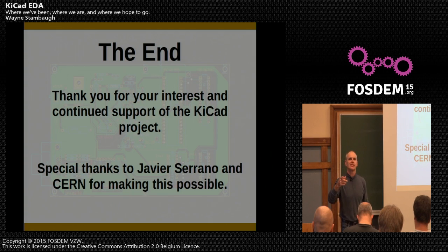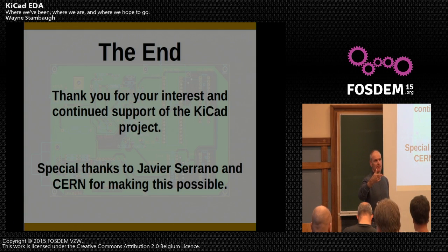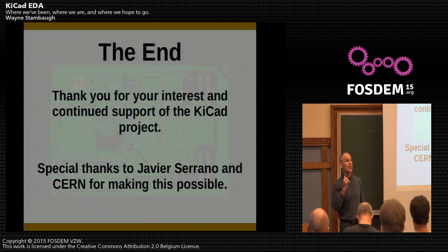Okay, the question is Eagle import, both libraries and boards, or just the libraries? Well, let me clarify that. Right now, only the footprint libraries and board import is supported, and that's only in the latest file format, which is XML, or an XML dialect, their newest version 8.